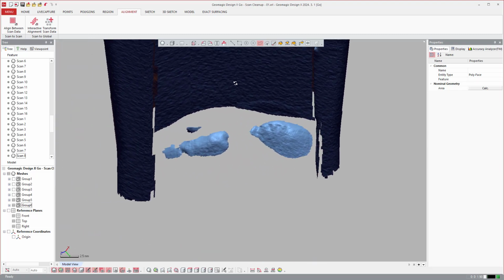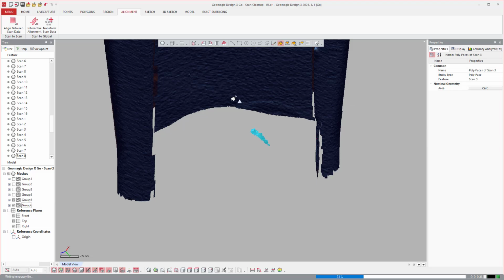You see here, this is another example where I can come in and I can just use the flood fill like this and hit delete and click on shells, and there's a duplicate shell there. You can see here like that, and it'll flood delete those. And I could flood click the main shell and then inverse if it was one piece, but this one is still multiple shells there.